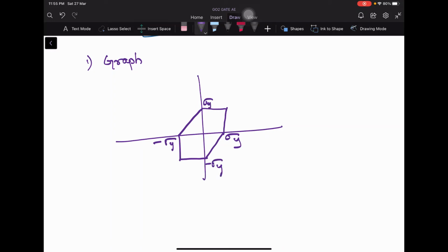So this is the maximum stress, in the sense the yielding stress marked here, and the region within this envelope is the safe region for your structure. Your structure will not fail within this envelope. So once it crosses your yield stress, the structure may fail.